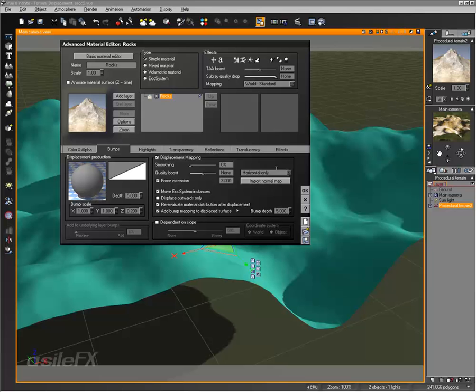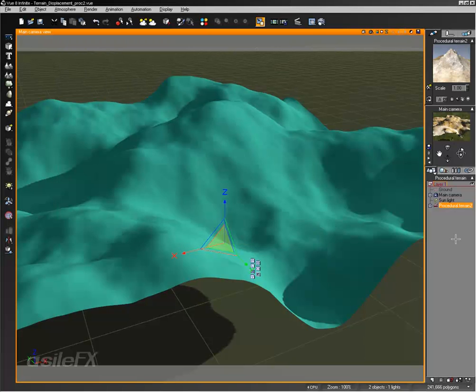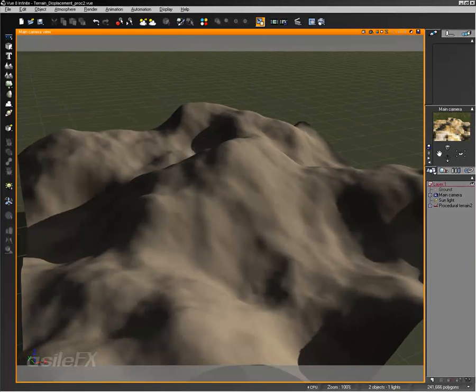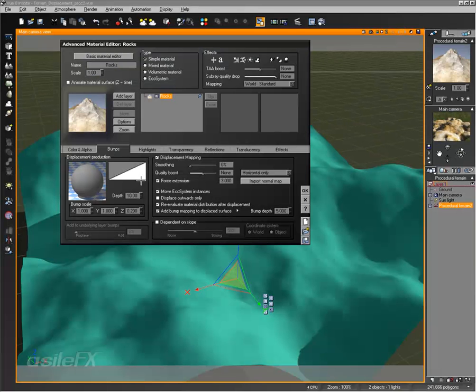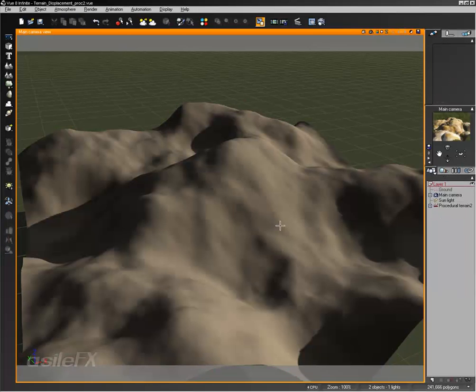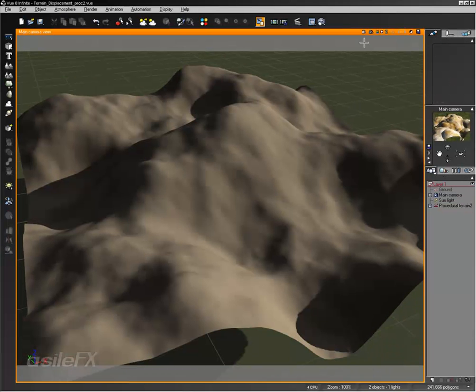Let's go ahead and take a look with some higher settings. Let's bring the depth up to 10. And I have made just a few modifications. I did reset that filter, and I'm going to take the Z and bring it to 0.4, because I did have that brought down to 0.2.